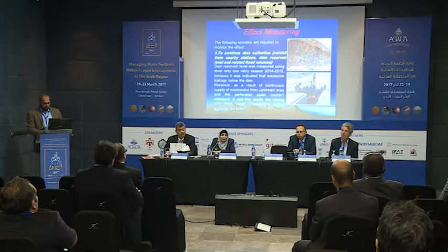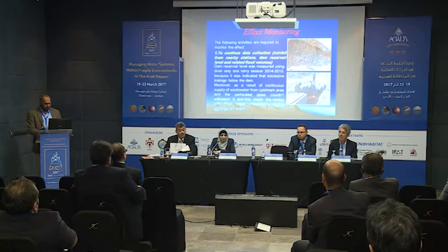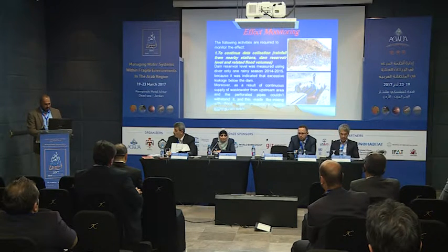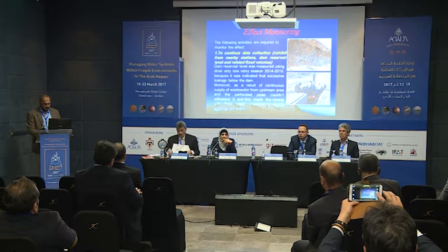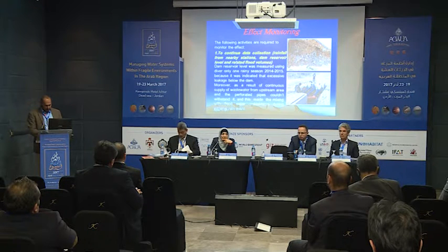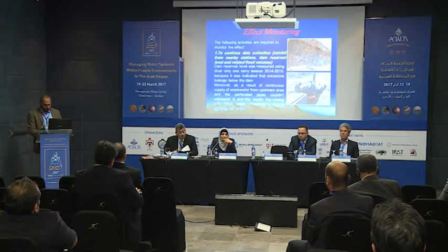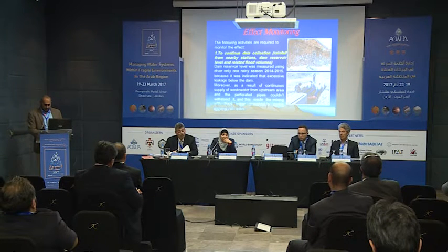Now we go to the effect monitoring of the dam. The activities required to monitor are to continue collecting the rainfall, the dam reservoir level and related flood volumes. Unfortunately, the monitoring was made for just one rainy season, because there was leakage below the dam, and we need at least 2 rainy seasons to exactly monitor the effects of this dam. Also, we have damage to the perforated pipes, which were used to collect the wastewater from the upper part of the dam, and this may cause mixing of the wastewater with the retarded water behind the dam.